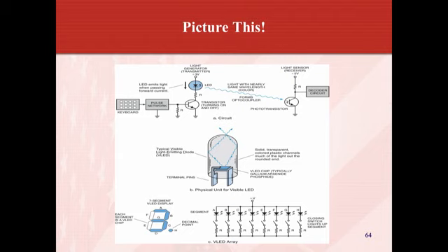Okay, this is an LED again. I guess it's showing your keyboard, and it's showing you a little bit of a circuit there. Pressing a key activates a pulse network, which then triggers a transistor to switch, and with 5 volts on the anode of the LED, current travels down in the direction of that arrow pointing toward the transistor, goes through the collector, which is the top, passes through the base a little bit, and then comes out the emitter, which is the arrow pointing to the ground there.